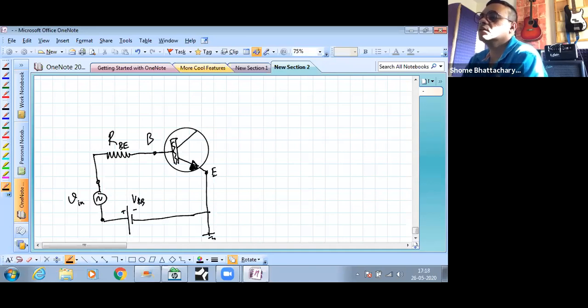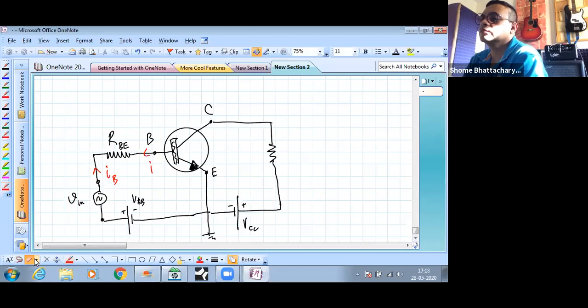On the other side, we connected the load resistor across the collector emitter junction. So because this input voltage made your base current become a fluctuating current, it's no longer a DC value, automatically our collector current also becomes a time varying one, and so does our emitter current.